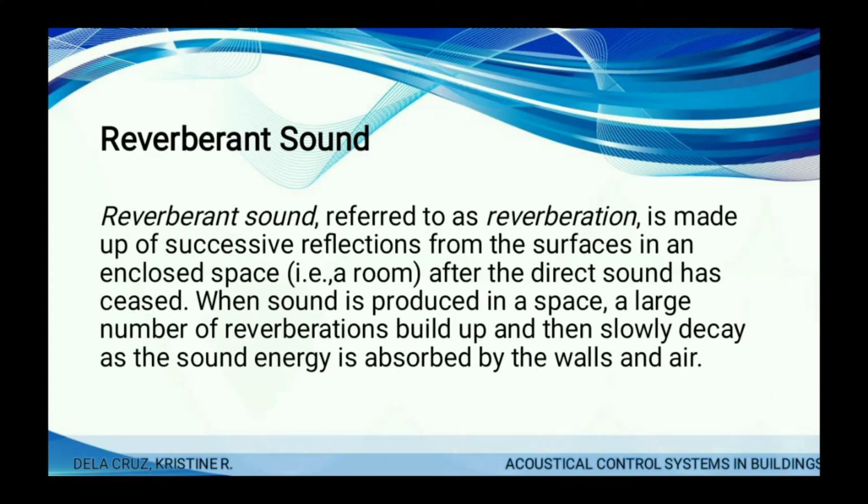So, reverberant sound, referred to as reverberation. When we say reverberation, ito nga yung numerous reflections of a sound. And it is made up of successive reflections from the surfaces in an enclosed space. After the direct sound has ceased, when sound is produced in a space, a large number of reverberations build up and then slowly decay as the sound energy is absorbed by the walls and the air.